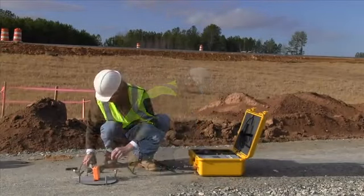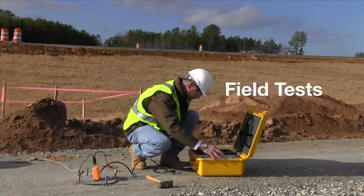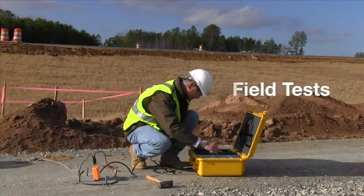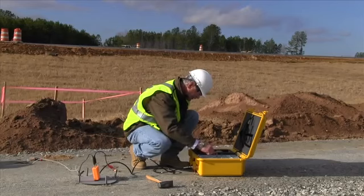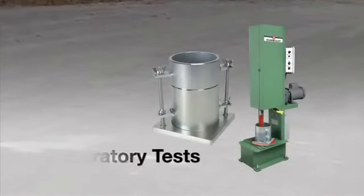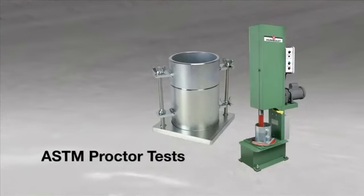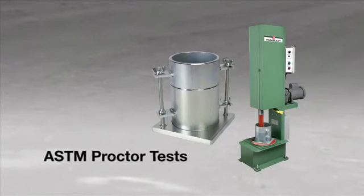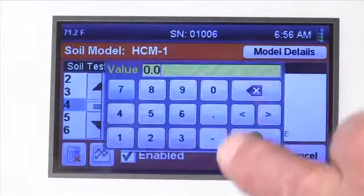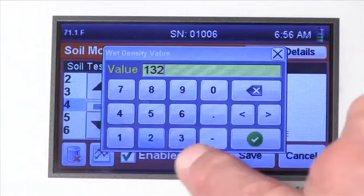Soil model data consists of two types of test data. Field tests, which collect the necessary data to create a working curve of densities and moisture, which relate to specific readings made by the EDG, and laboratory tests, which consist of the standard ASTM Proctor tests used to determine the compaction characteristics of the material to be tested. The results of these tests will be entered into the EDG to help it determine the percent compaction readings.